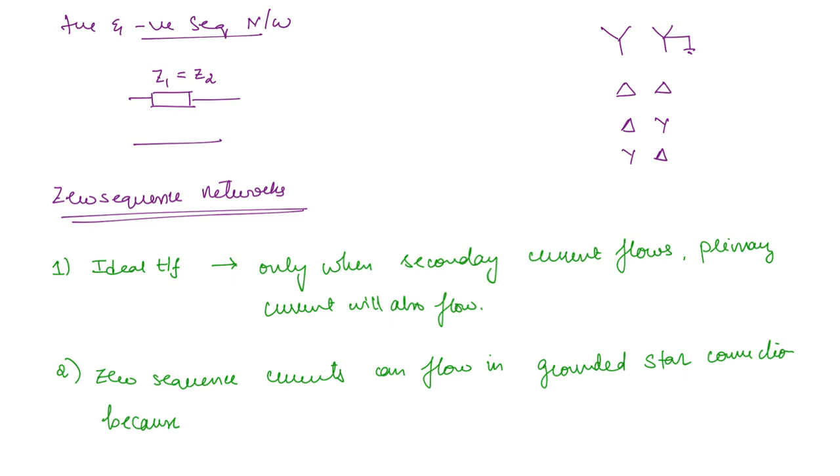These are three-phase balanced systems in a conventional sense, so if you add all of these currents, they will be zero. But if you take zero sequence currents and add them, they are not going to cancel each other out. There needs to be a return path. When there is a ground connection, a return path is available. Ground provides a return path.